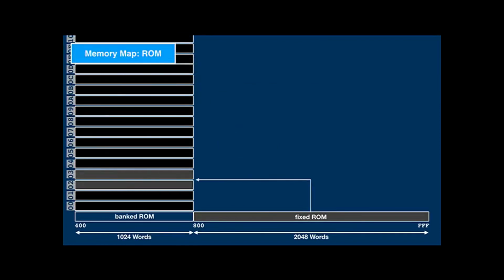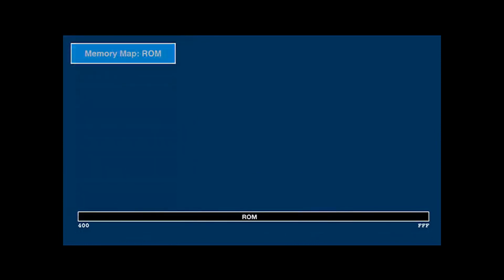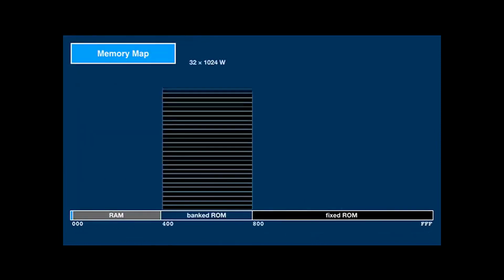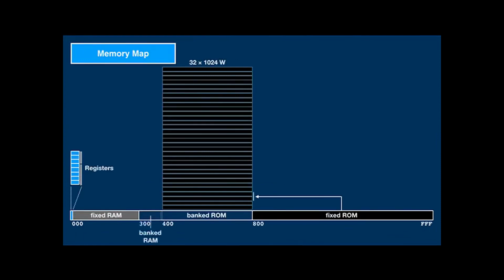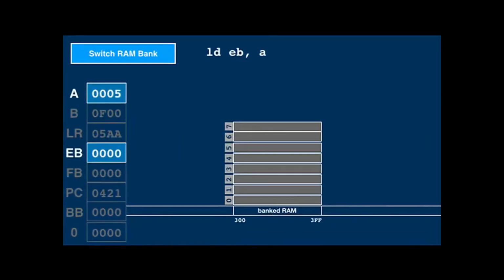The fixed ROM area will always show the same contents as 2 of the ROM banks. The designers chose banks 2 and 3 to simplify address encoding. In practice, fixed ROM contains core operating system code and fixed RAM core operating system data that have to be available at all times. The remaining functionality is distributed across the different ROM and RAM banks.